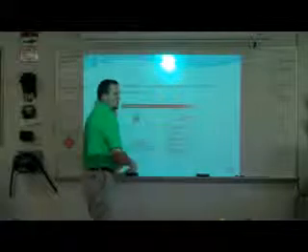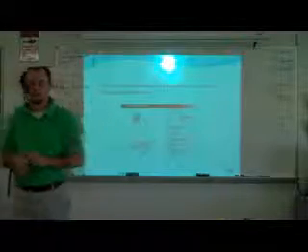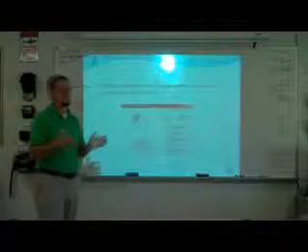We get back to some of the rules from last chapter. How many feet apart horizontally should receptacles be? 12 feet. 12 feet. Okay? Means no spot on the wall should be more than 6 foot from a receptacle.